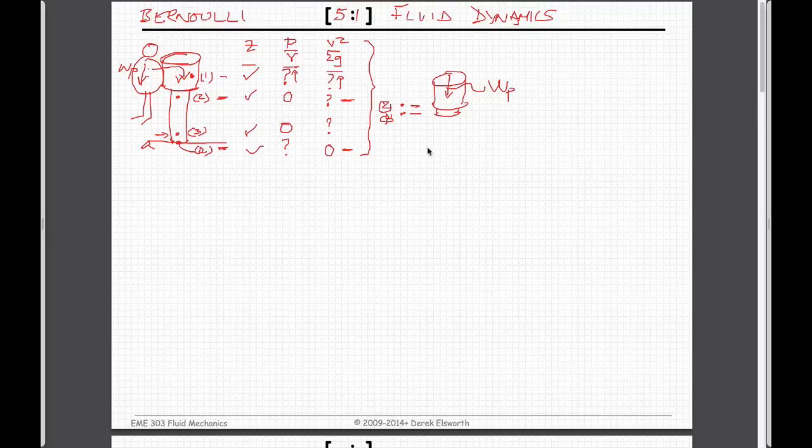So in other words, it's the amount of force we have to do to get us off the ground in the first place, not to get us 10 meters up or however far up we are. And so then we can write our equations exactly for that. We can write Bernoulli. So what's Bernoulli going to look like? It's going to look like Z2 plus the pressure at point 2 divided by the unit weight plus V2 squared over 2g, and it has to be equal to the magnitudes at point 4. Again, pressure, unit weight, plus velocity 1 squared over 2g.